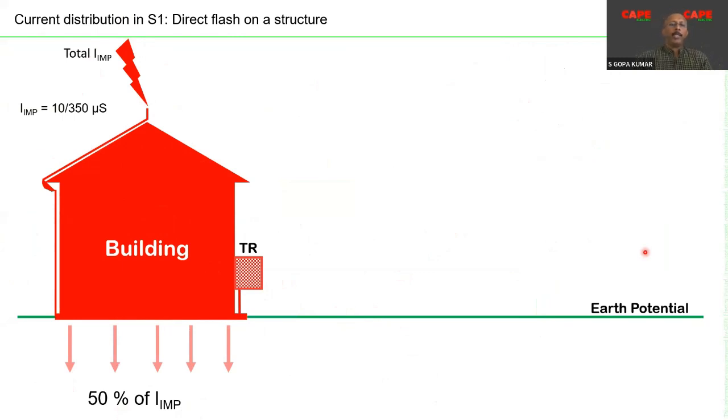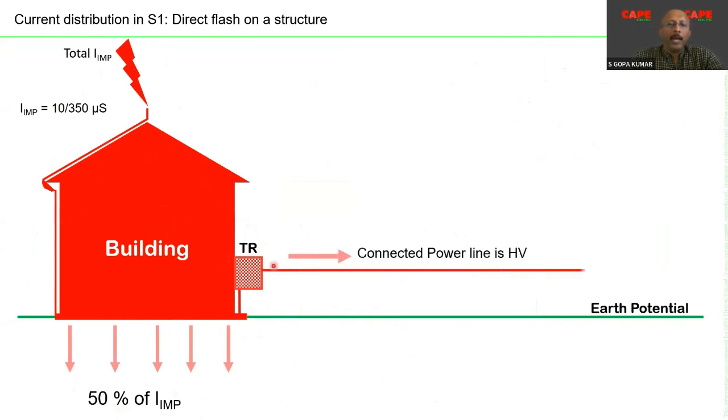You also should understand that in large buildings, for example industrial buildings or nowadays commercial multi-storied buildings, the transformer is always a part of the building, inside the building. Under this condition, if the equipotential bonding is properly made along with the neutral earthing and the body earthing of the transformer, there is no low voltage service line connected.